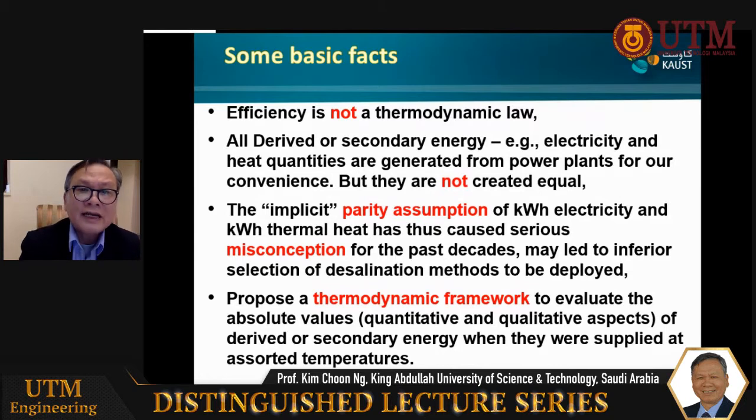As you know, all the secondary energy or derived energy comes from converting primary energy in power plants. And because of the disproportionate destruction of the available work or exergy from this primary energy, they are not created equal. Therefore, the implicit parity assumption of 1 kilowatt hour electricity being the same as 1 kilowatt hour thermal may cause serious misconception.